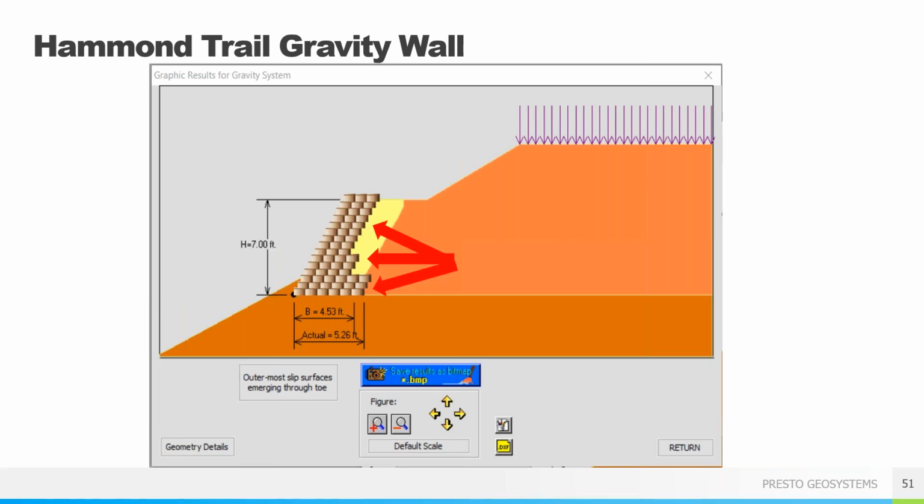As you can see, we have 3 steps worth of panels, starting with 6 cells at the base, moving to 4, and finally moving to 3 at the top. If you remember back to that design data, whatever number of steps you select, it's always going to print out what it gives for the different types. Like I said, I always like to have a maximum of 2 different types of panels, so it's not as hard to construct in the field.